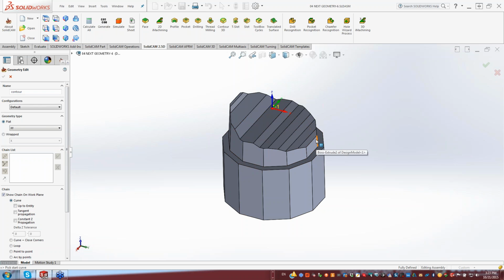I'm going to click on this line over here, the first edge. Note the arrow that it's in the direction that it's going to over here. I'm just going to click on Add Selected Element, this button over here. And as you see, it's just going around the part. Every single time I click on it, it's going in the direction that the arrow is showing me. Now I finished creating a geometry. You can see how quickly that was created. Okay. Now, there's one more option that I did not have in my presentation that I'd like to show you.